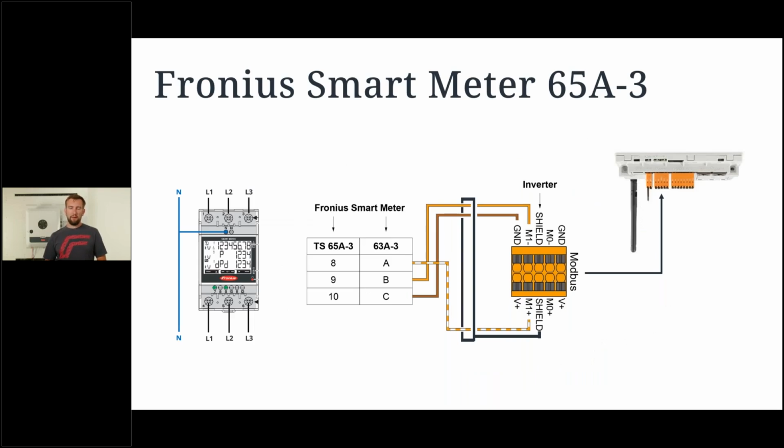Putting that together, we then have a contact where we have our full smart meter and we have our plug then on the data pilot on the inverter. We've already got the wires in place, but there's something missing. We've got wires, we've got a shield, we're still missing a termination resistance. And that 120 ohm termination resistance has to go at the ends of this communication.